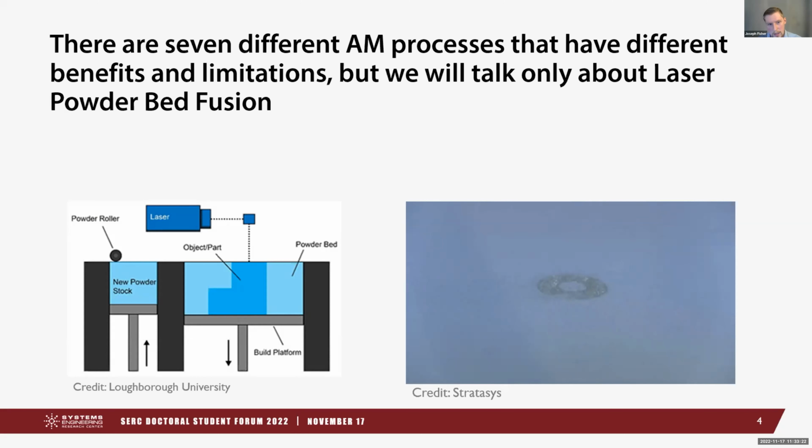And then a little animation showing you. So you see the powder gets spread across, the laser hits it, creates your shape, drops, new powder comes across, and it just repeats and repeats with whatever each individual layer looks like until you create your whole part.